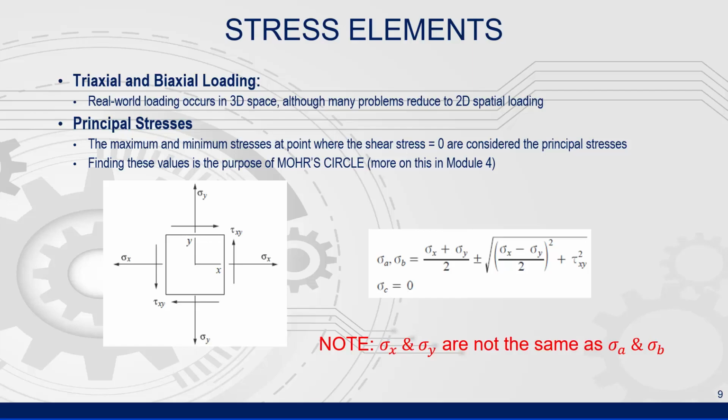There are three applications of stresses to a given element. The first is the actual applied stresses. This could be a bending stress, a shear stress, a direct stress, or a torsional stress. As we create our stress element, these stresses are applied and sometimes combined to be axial or planar stresses. Thus, we end up with normal stress in the X, Y, and/or Z axes, as well as shear stress in the XY, XZ, and/or YZ planes.